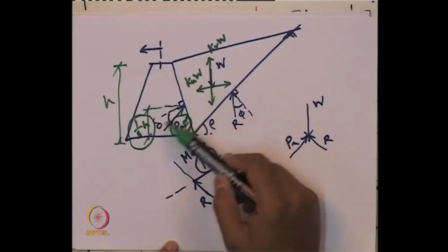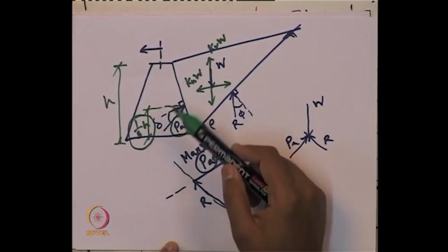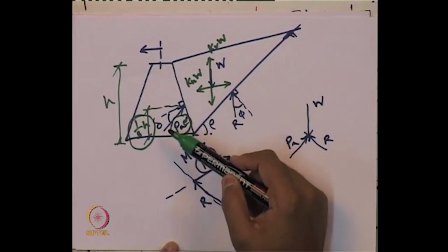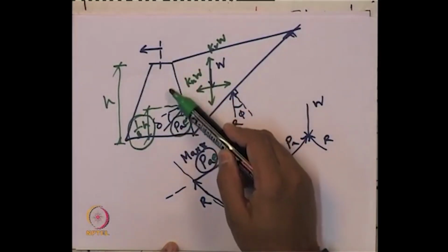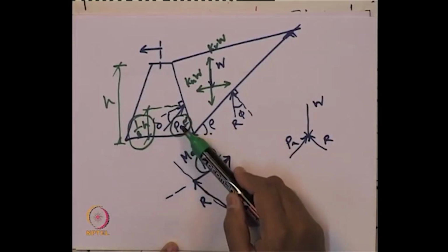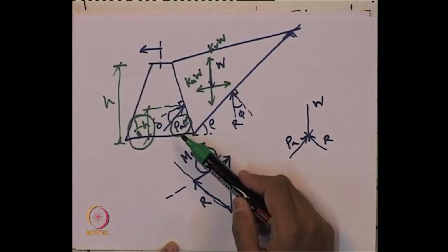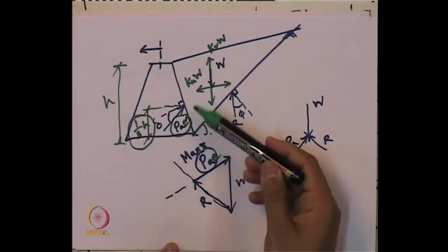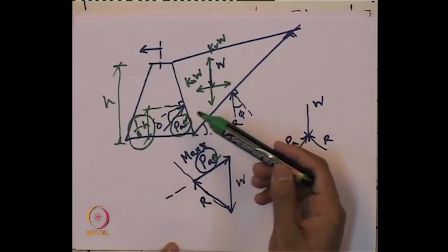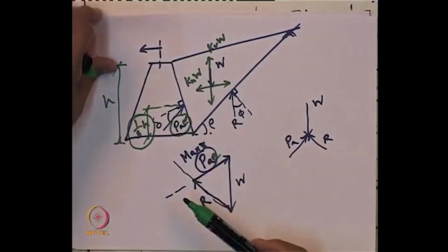but to put the reinforcement in the wall, suppose you are going to use a reinforced concrete wall as a retaining wall, you need to know how much reinforcement at different levels you are going to put, and for that you should know the distribution or exact point of application of this PAE, so that accordingly you can place your reinforcement, right. So, the point of application should also be known, and that also takes care of your sliding analysis, rotational analysis, everything, because in every case the point of application is an important parameter.